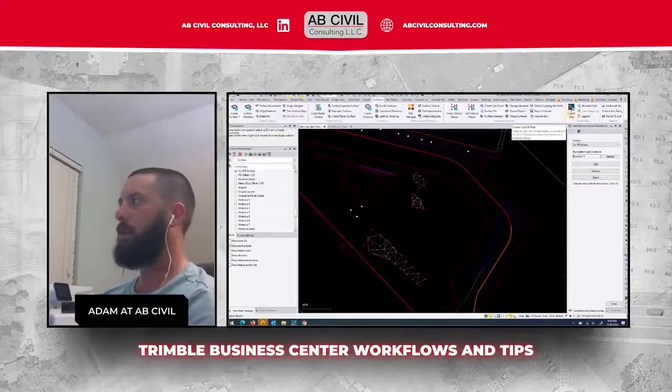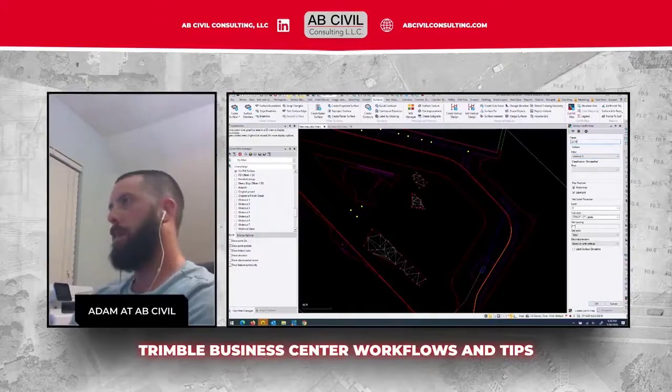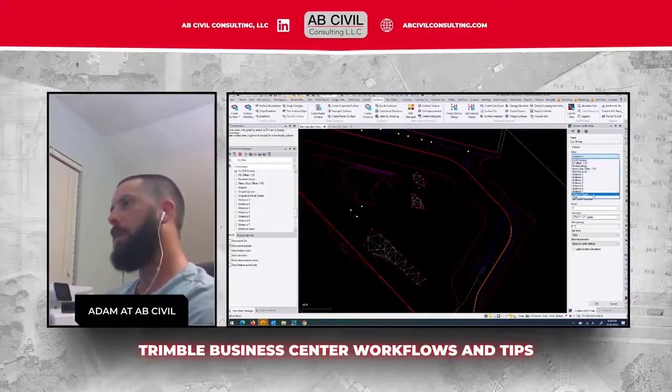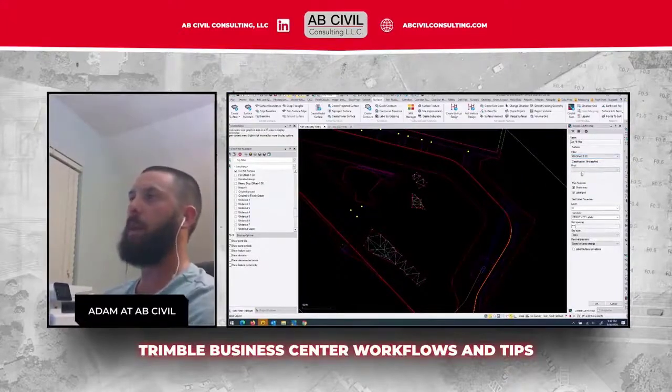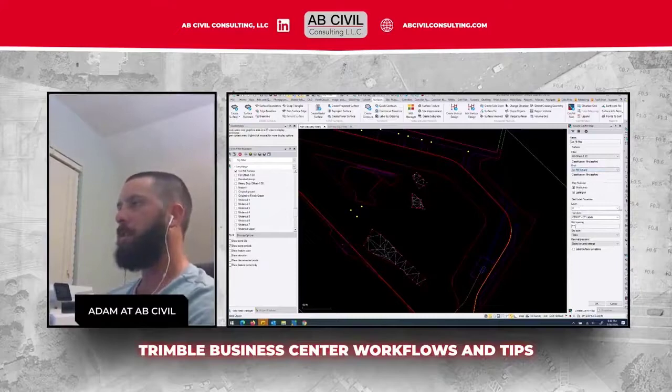And then, simple as cut fill map. Name it. So my initial surface, I'll do this backwards so it makes more sense to most people. I'm going to do my finished offset minus 1.33 as my initial. So the subgrade surface is what I want to use as my initial. And then I'm going to pick the cut fill surface as the final.